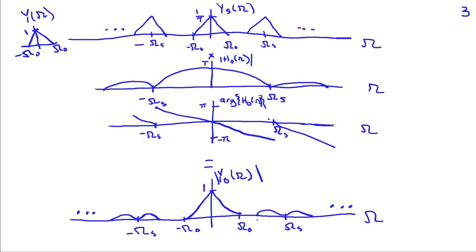And that explains the sharp, stair-step character of the time domain signal. To have those sharp edges, we need higher frequency components in the spectrum, and so those are there at multiples of omega sub s. So clearly, the spectrum of the output of the zero-order hold does not match the spectrum of the original signal. We have a little bit of work to do yet to reconstruct this original signal. Oh, I also forgot to mention when I graphed h0 that the magnitude at omega equals 0 is T, so that does compensate for the 1 over T that was in y s of omega.